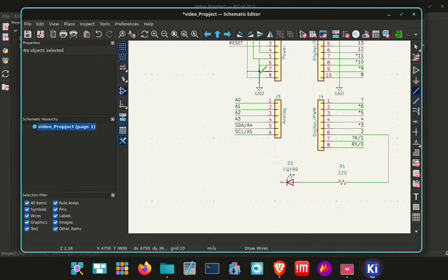If I just select left click the ground button, the circle there, and I come down here, it's gone all the way across those lines. Now I always like a bit of management on this, so I come out, I left click there, and then I'll come down, because I don't think the auto routing works very well on it. It works about 60% of the time.